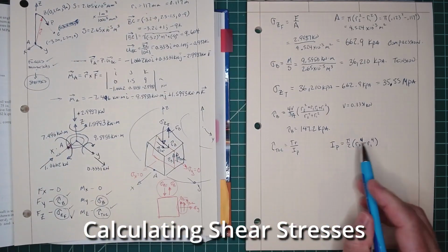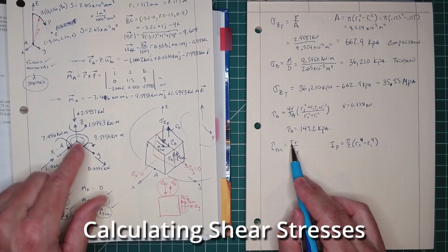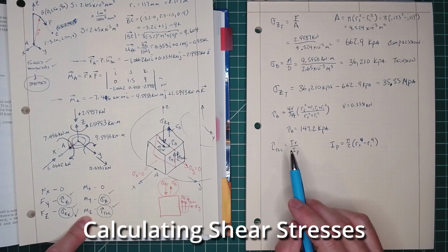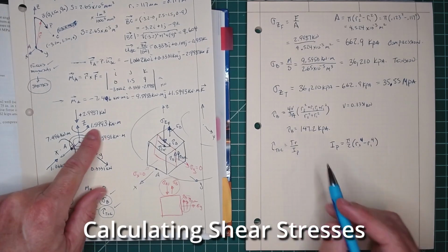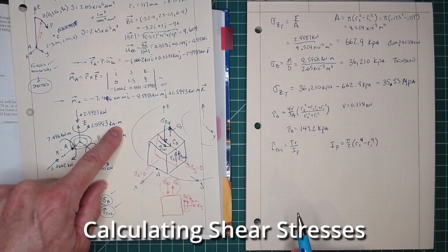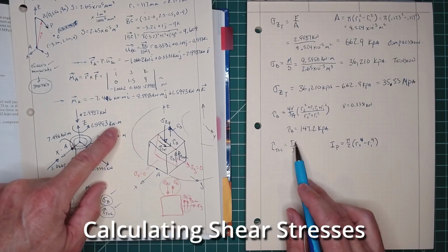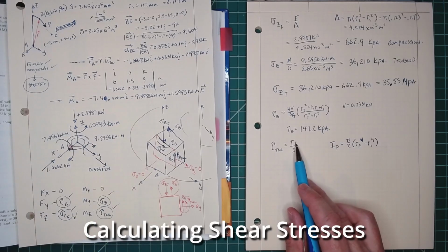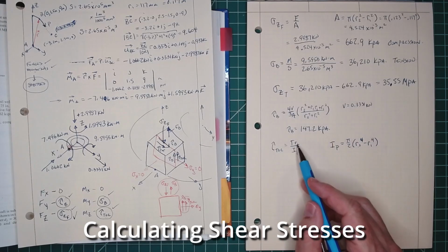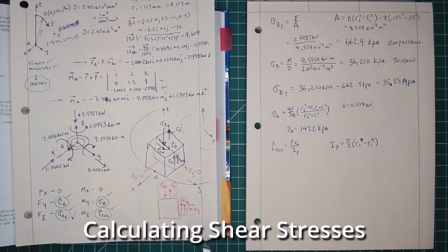At this point, we know R2, we know R1, we know our torque. Our torque is our moment about Z here, which is 1.5993 kilonewton meters. And our R here is the maximum, the outer fiber, so that's R2, which gives us our max, the point that A is on.